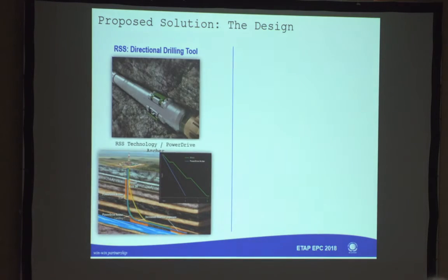To apply our solution, we need to redesign the BHA, the drilling BHA, to drill this and acquire the needed data for us to take the decision. On one hand, we need the drilling technology, the rotary steerable technology, RSS, that can control the direction of the trajectory in 3 dimensions, and also enable us to minimize the vertical section or the kickoff point parameters for the trajectory.